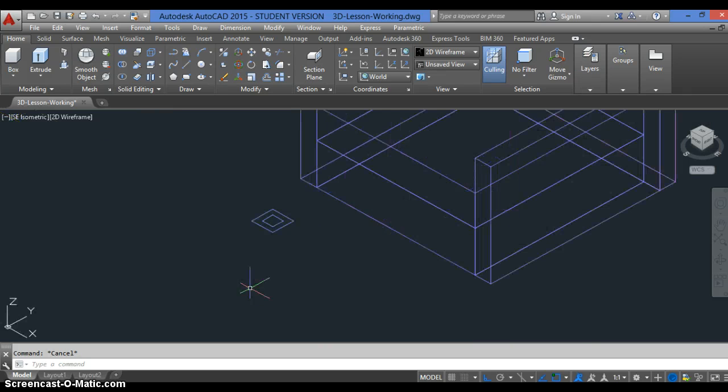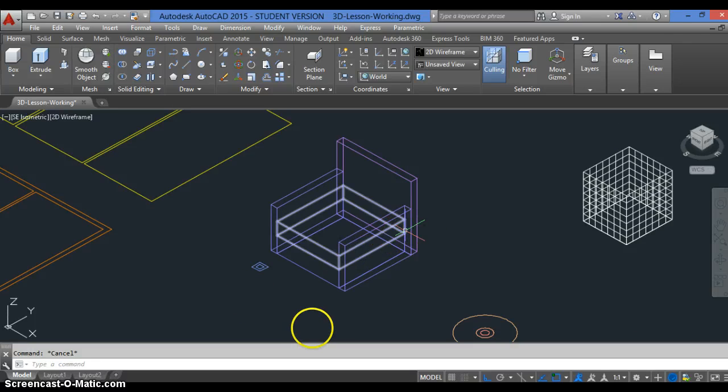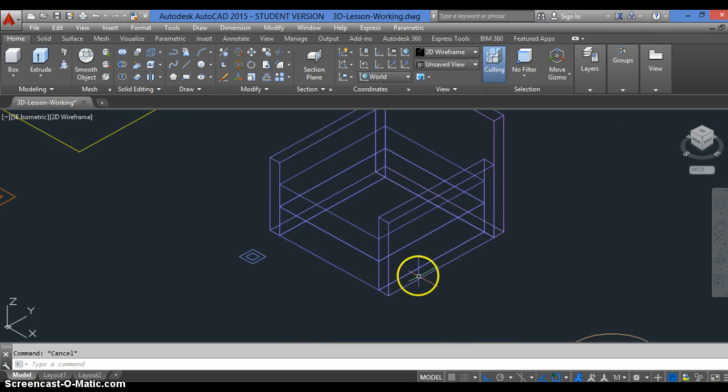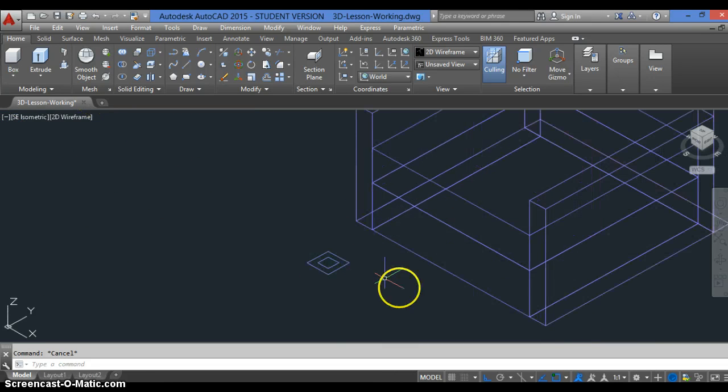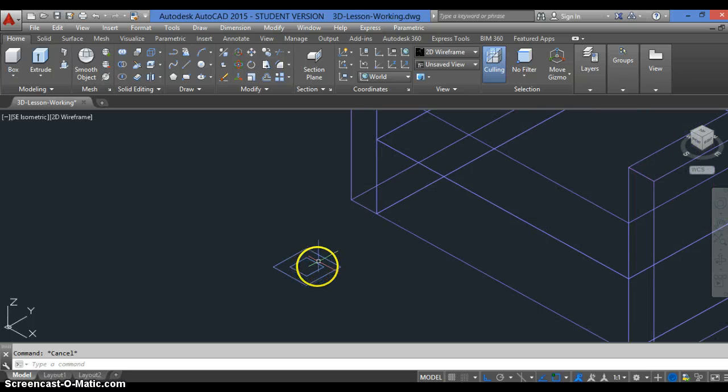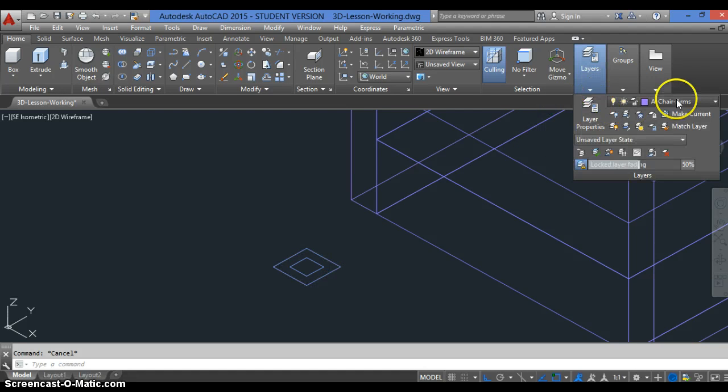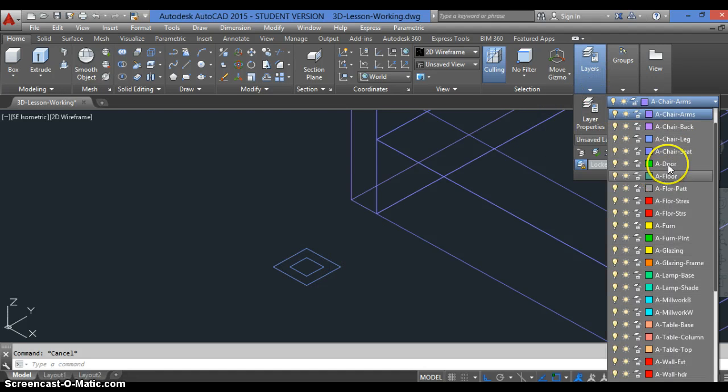Okay. Now, we want to make a leg for our chair. We don't want it to sit on the floor. So, I kind of want a tapered leg, meaning that the leg would be about 2 inches at the bottom and taper up to 4 inches. So to achieve that, I have drawn a 2-inch rectangle and a 4-inch rectangle. And we'll change our layers to the leg layer.